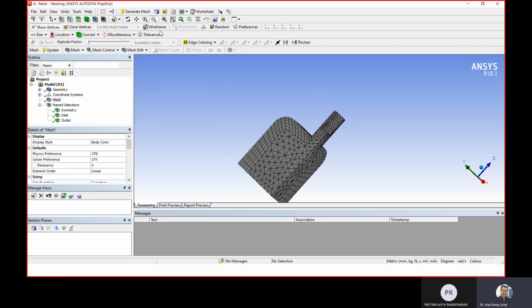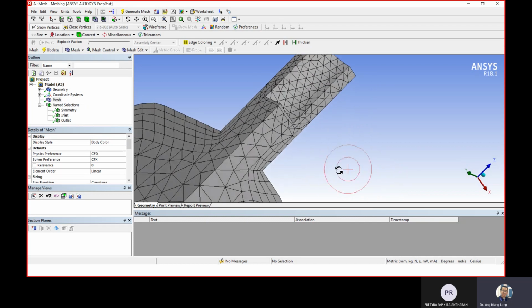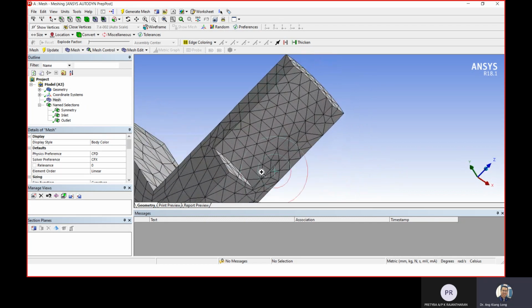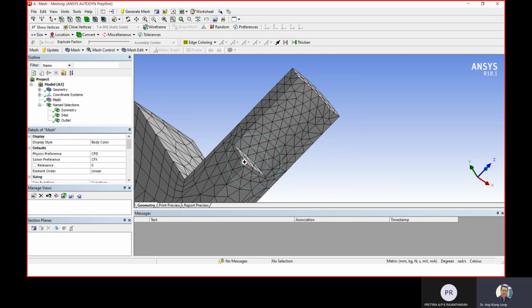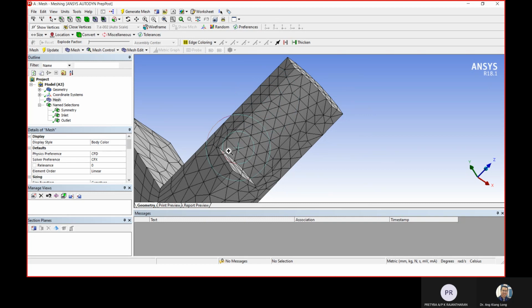And then you zoom in on this region again. Do you see the differences from the previous example that you saw? Just now you saw 5 layers, right? Now no more 5 layers. It will just mesh according to the topography. There's no 5-layer inflation here. Do you see it?